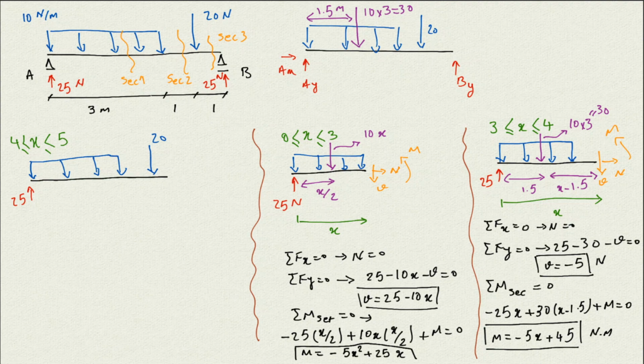And if I go ahead and replace that distributed load with the resultant force, again it's going to be the entire force is there, so it's going to be 10 times 3, so it's going to be 30. And the distances we have, again the x is going to be all the way from here to here, so that's the x. That's what we have for the x, and that is the other we know, and also the internal forces themselves.